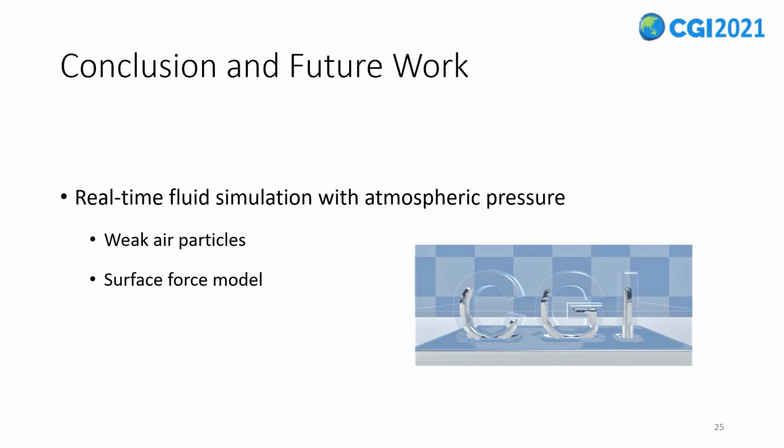For conclusion, we have presented a comprehensive solution for real-time fluid simulation with atmospheric pressure. We introduce weak air particles to weakly couple with the liquid and track the liquid surface under atmospheric pressure, and presented a novel surface model composed of density-related atmospheric pressure force and surface tension force.